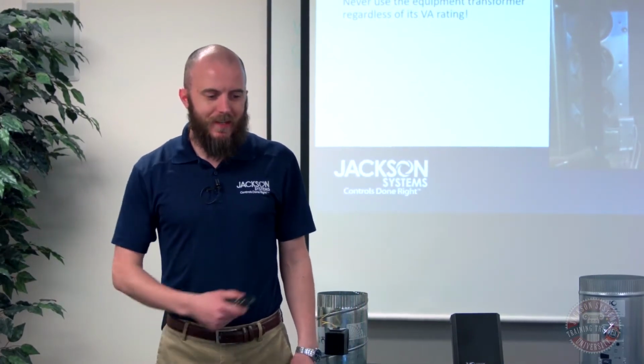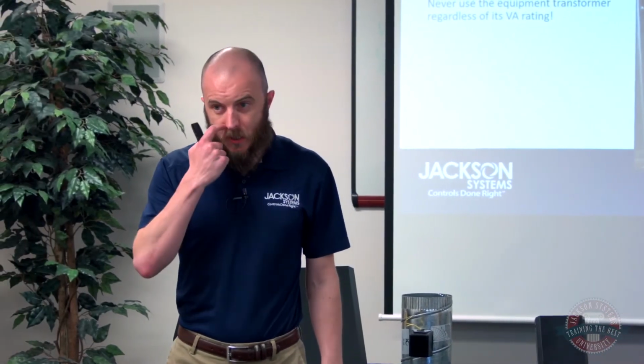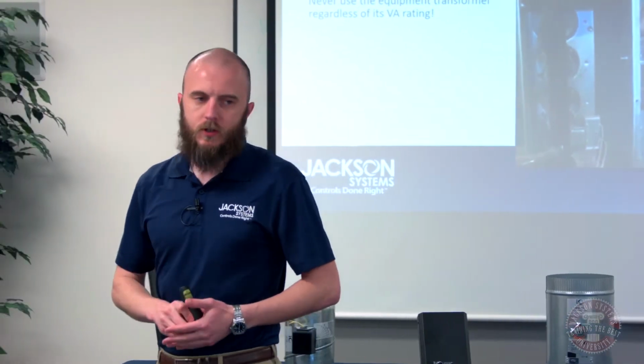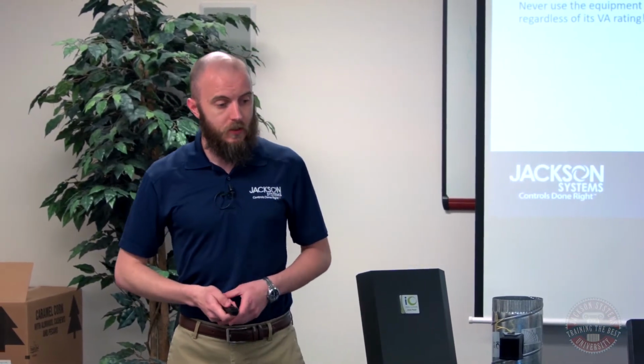Never use the equipment transformer regardless of its VA rating. That's just a standard rule of thumb. We always recommend just always install a separate transformer. Most zone panels have electrical isolation, dry contacts between the panel and the equipment, so you don't have to worry about having separate transformers. You don't have to worry about any phase issues there or anything. So just always install a separate transformer, and you don't have to worry about what kind of load you're putting on that thing.